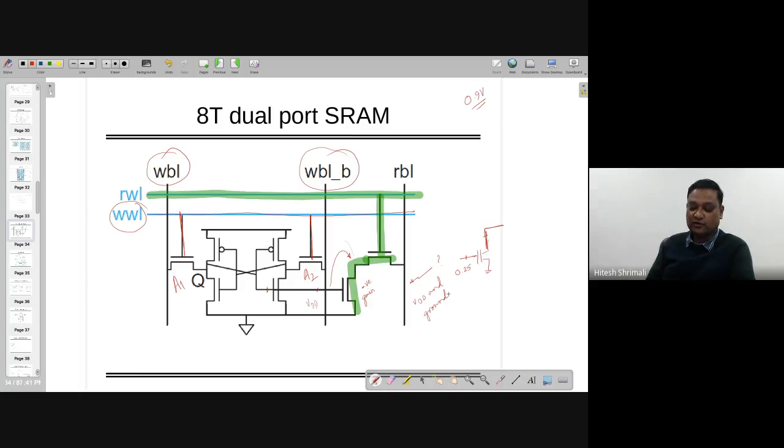So this is going to give you efficient read operation, and of course it's going to increase read margin, which is going to be exactly equal to what was happening for the hold margin, because you are reading directly from the cell. You don't use access transistor. If you are using access transistor, then its whole story is coming, and one of the sides is connected to VDD, and because of this recharge operation, both are connected to VDD, and it's going to give you the operation which is not required, or you can say that which is going to reduce the read margin.